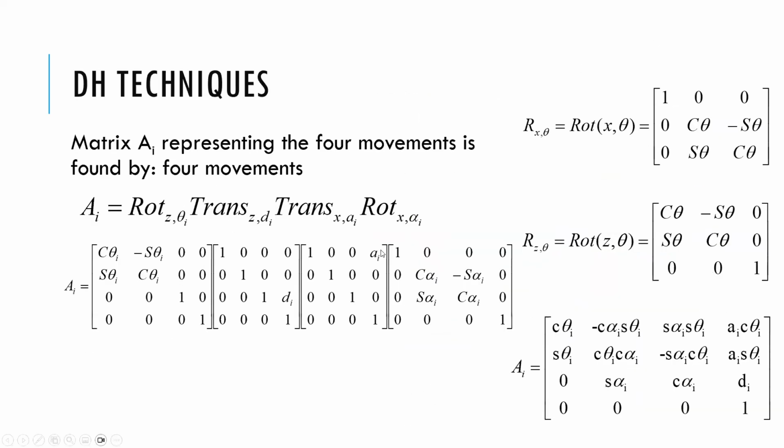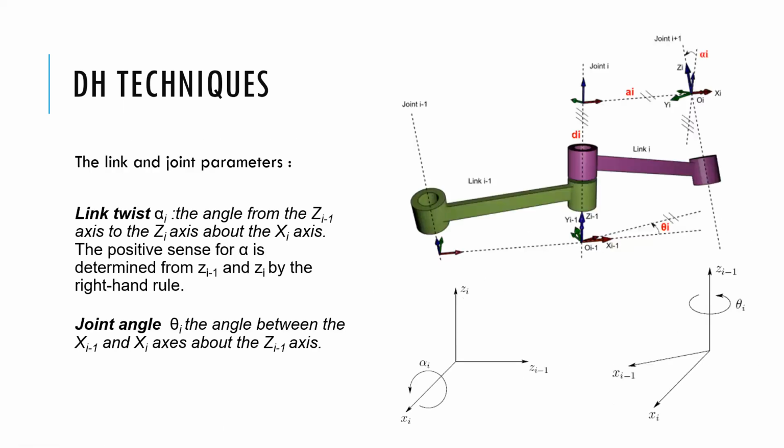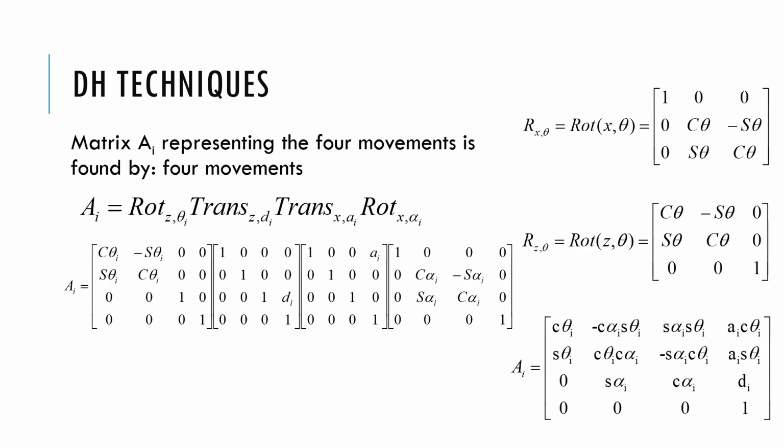And this is the original transformation, and then some books actually use, you might see a i-1 and alpha i-1, and so they use a different order here, and you have a different A matrix for that. That's the modified DH table that certain books use. The older books, like Craig Robotics, use that, and certain older professors still use that method as well. And I used the original one. It's still a series of 4 movements. It's a different A matrix, but however you get there, you're still going to get to the same spot.